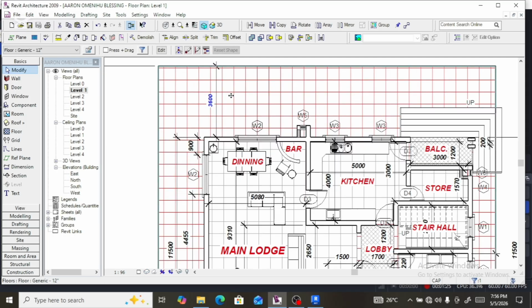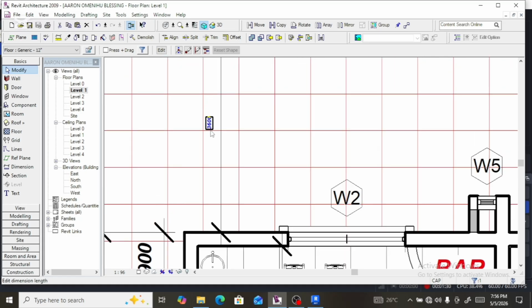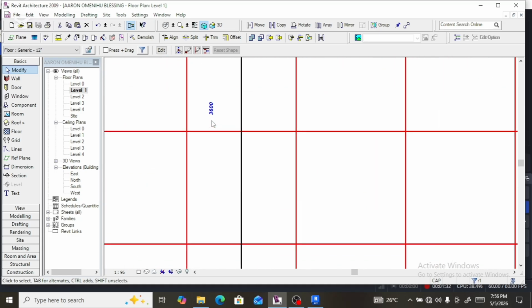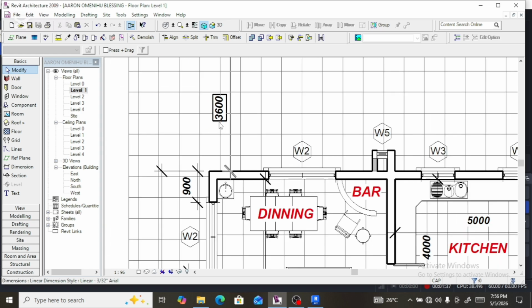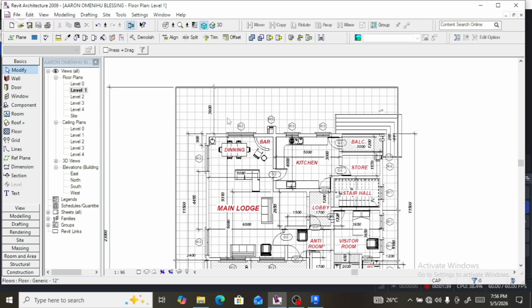In the floor plan, between this area to this area, I'm leaving 3.6 meters. The reason is not because of the back view, but because we're going to place a tank stand here. The tank stand should be sitting on a minimal space of 2 meters on its width.